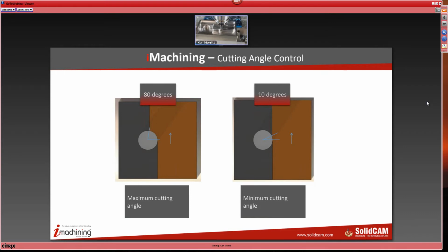That's the maximum range in our algorithm. Why the 80 degrees? Well, we noticed through practical testing and working with this and looking at the machines, feeling them, looking at spindle loads and everything, somewhere between 85 and 90 degrees, depending on the ratio of rotational velocity to forward velocity, we begin to see that pressure vector oscillation begin. Now, it never really fully flips to the outside like you saw earlier until right at the 90-degree quadrant.